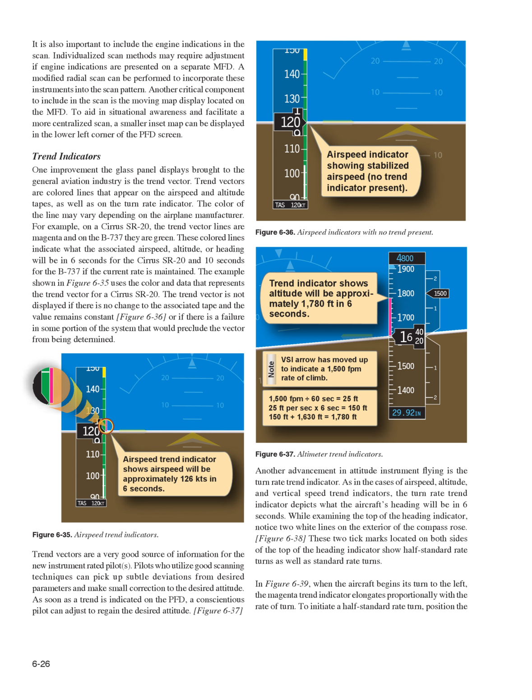Another advancement in attitude instrument flying is the turn rate trend indicator. As in the cases of airspeed, altitude, and vertical speed trend indicators, the turn rate trend indicator depicts what the aircraft's heading will be in 6 seconds.